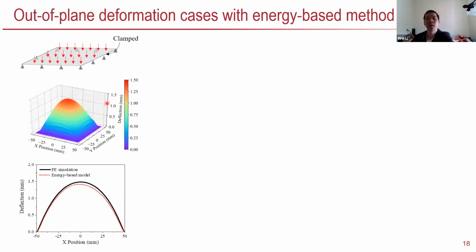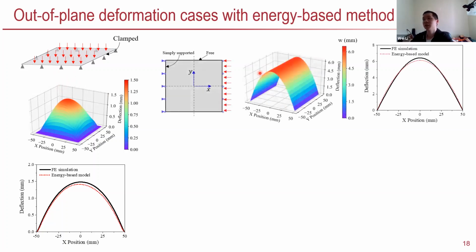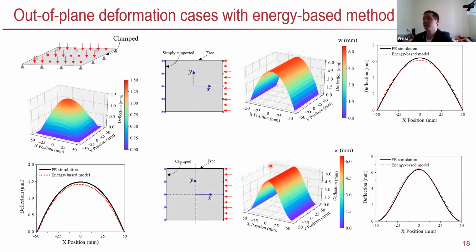And then we also try this energy method with some out-of-plane cases, for example, the out-of-plane deformation with the plate, and even some buckling analysis. Like if we compress a thin plate from the in-plane direction, it will buckle to an out-of-plane shape. So with the energy-based method, we can also predict this kind of problem.